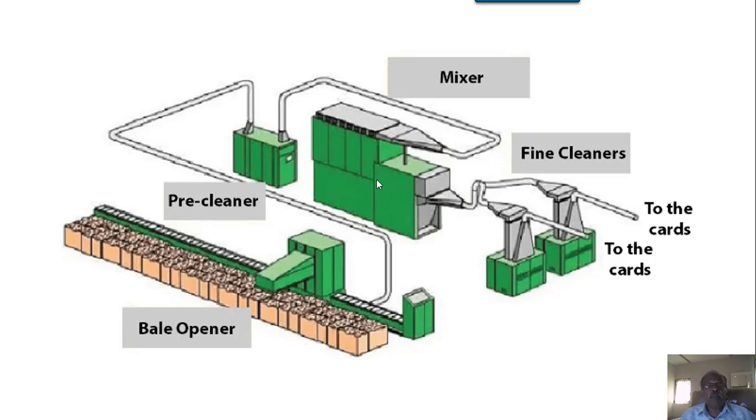In these compartments, the tufts will fall down as per the requirement, and the height is adjusted, and sensors are there. Centrally, whether feeding is required or not is sensed, and per chamber, whether cotton is to be dropped or not is again adjusted through pneumatic sensors, thermopneumatic sensors, etc.